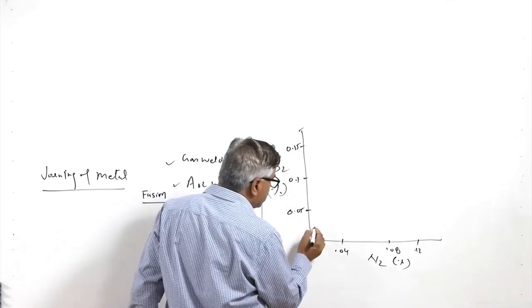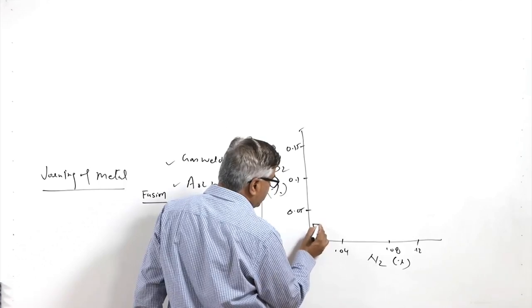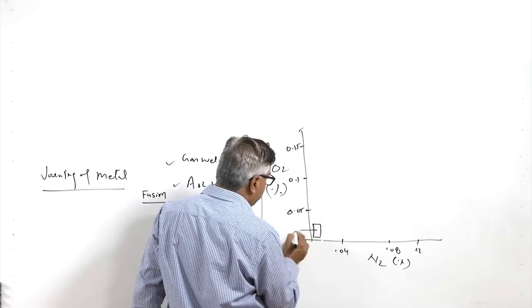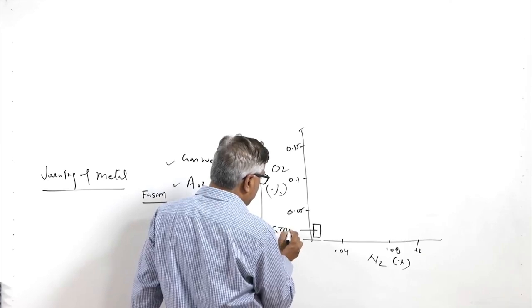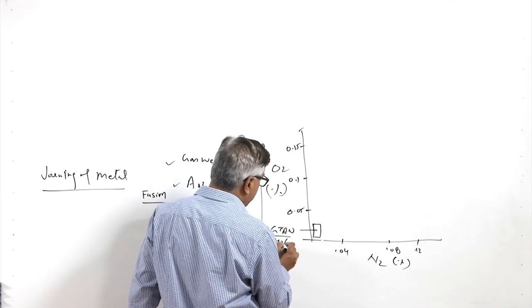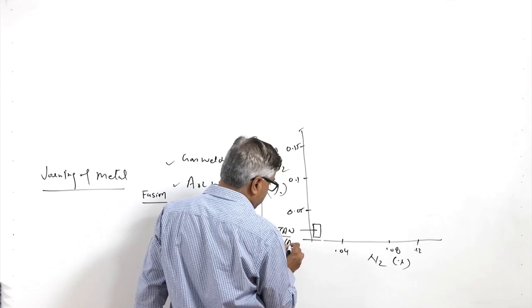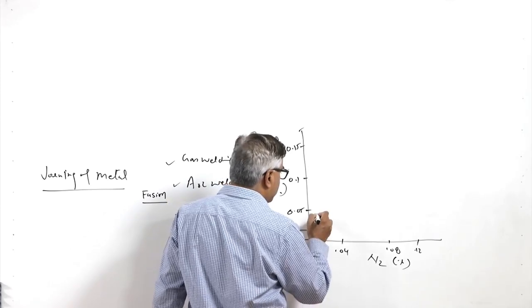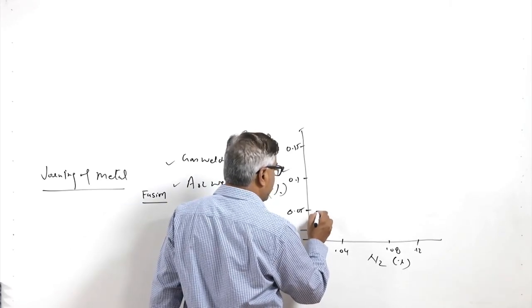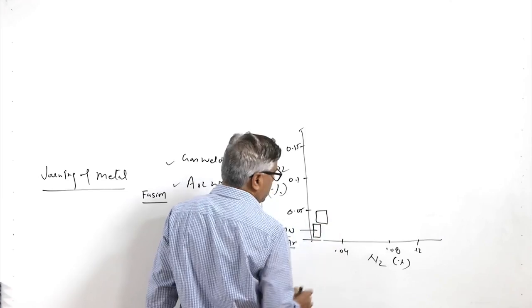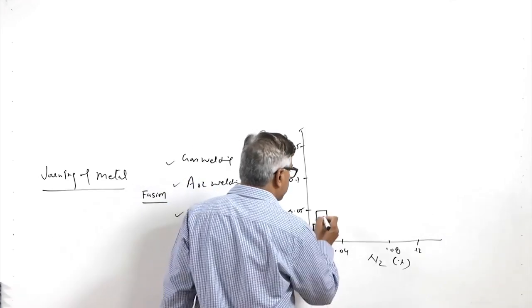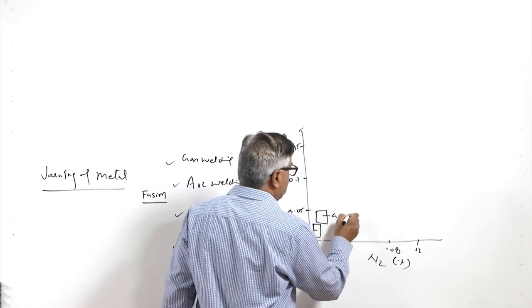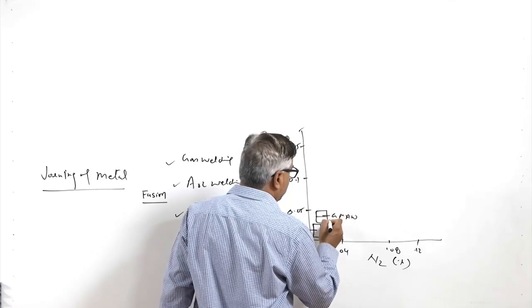With regard to this, the cleanest weld is produced by the TIG welding process, GTAW, when we are using helium or argon, but somewhat more oxygen and somewhat more nitrogen is produced when GMAW uses inert gas.